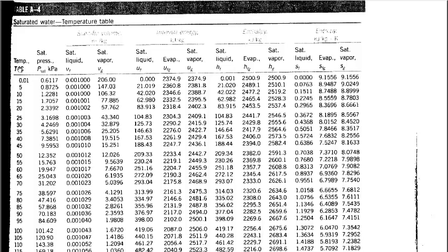So that's our temperature data, our saturated pressure data, and now the next sets of data all correspond to the four major properties that we'll study this semester. So there's the specific volume data, there's internal energy data, there's enthalpy data, and then there's entropy data. And you'll notice that there's at least two columns for each property. There's the saturated liquid column, and there's the saturated vapor column. So the data in the saturated liquid column is telling us the values of the substance when it's a saturated liquid as a function of the saturation temperature, okay?